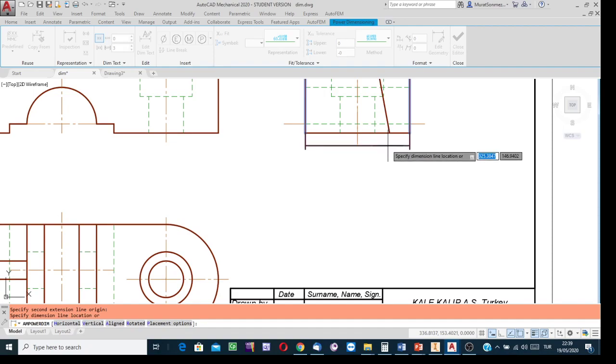But when the cursor, together with the dimension line in the simulation, reaches the place where the distance is 10 millimeters, then there will be such highlighting and jumping, you see. While I'm moving the cursor slowly, it is not under my control. The simulated dimension line jumped ahead. And now the extension and dimension lines are not in the color which I selected for the dimensioning layer.